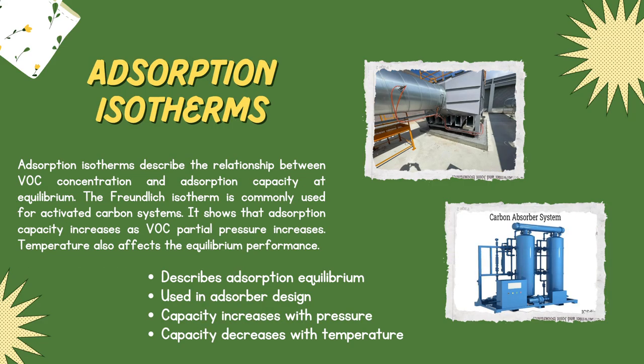Next, we jump into the adsorption isotherms. The isotherms describe the relationship between the VOC concentration and adsorption capacity at equilibrium. The Freundlich isotherm is commonly used for activated carbon systems. It shows that adsorption capacity increases as VOC partial pressure increases. The temperature also affects the equilibrium performance.